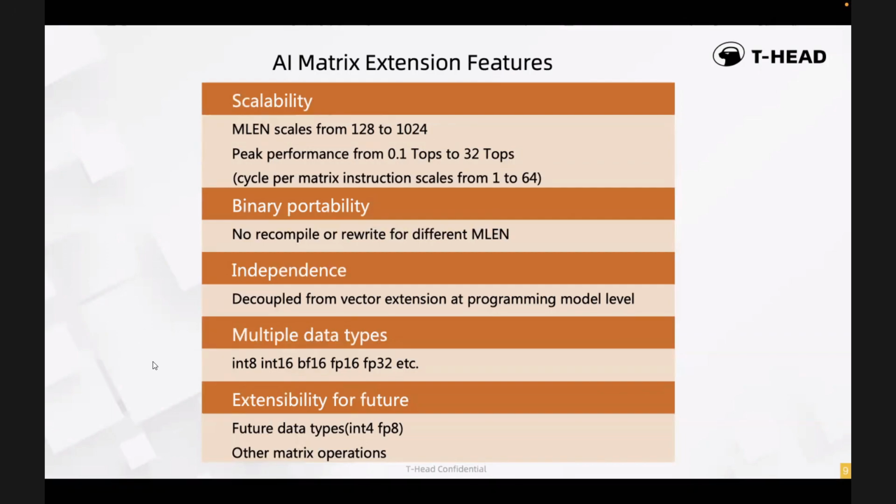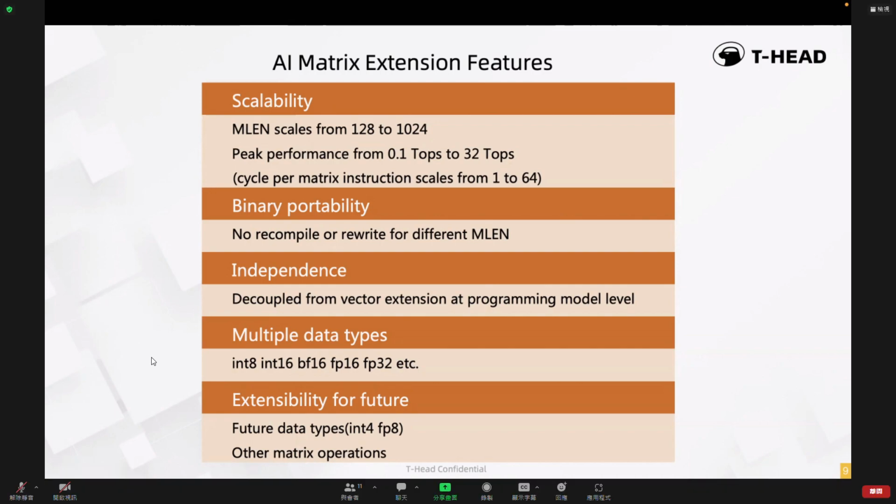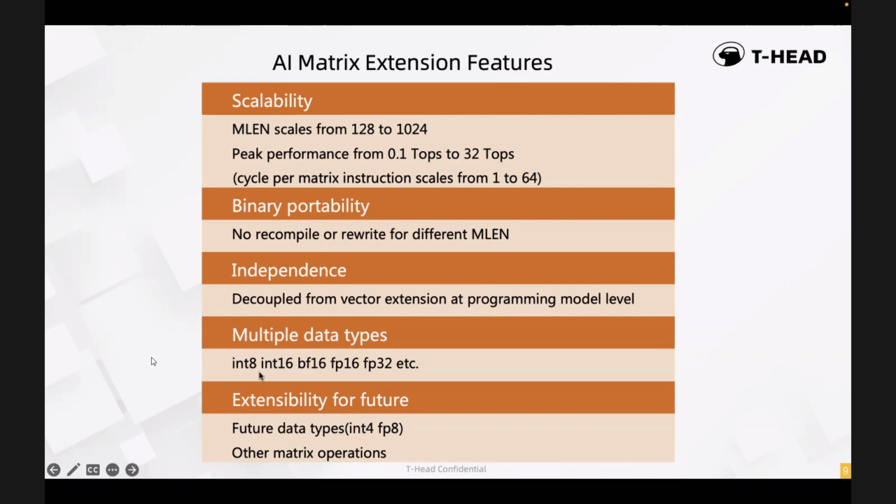For example, if the chip is used in training, FP32 and even FP64 will be supported first. If the chip is used in IoT devices, integer 8 is the only data type you need to support in the chip. Of course, if necessary, you can also give priority to extending new data types such as FP8 and TensorFloat 32.